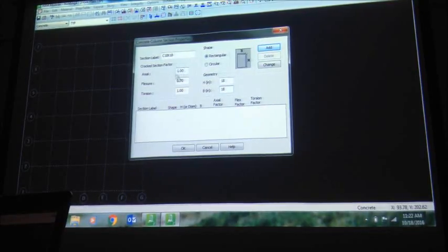Cracked section factor, these are code defined. These are the, obviously this is 1.7 and 1. If you are practicing in California, these numbers are actually 0.5, 0.5, 1. Okay. No, actually 0.5, 0.5, 0.5. Okay, these are the one in especially in seismic zone. Right now we are using the default values. We are not going to change it because these ones depends on what type of building and where you are located. Okay, what type of seismic category. It's a rectangular section, and I will say add.